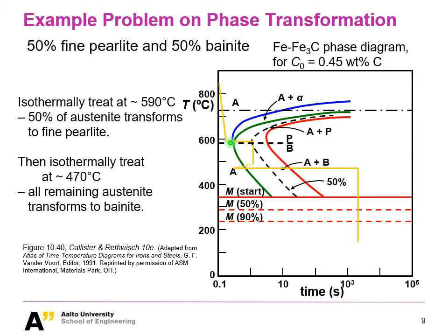So that is referring to we will have rather fine perlite. Yeah, that's the key here. And so you go to a rather low temperature with a fast cooling rate, and then you're just holding it. So you're doing an isothermal phase transformation, but you don't complete it.